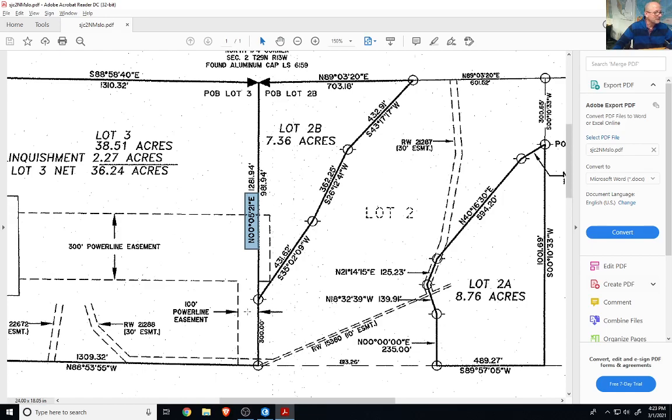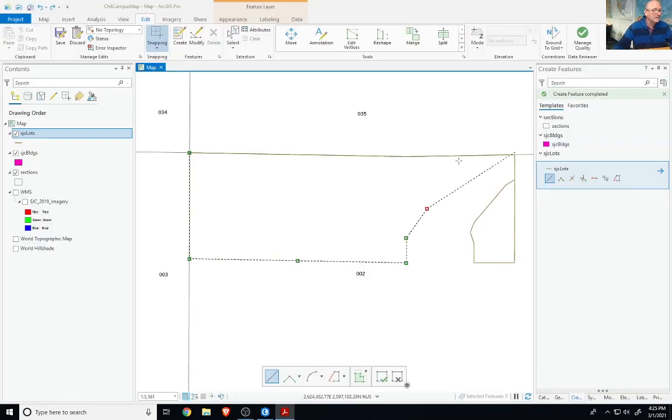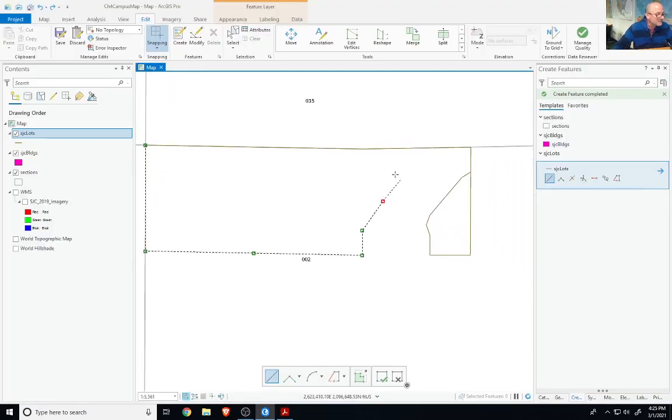So since I can just connect that, I'm just going to take these next three lines, close that off, and then close this bottom line off, and this line, and that's probably going to do it, I think. So when I'm drawing in here, this is the last line before I can just connect to the top of the line that I've already drawn where there's a vertex waiting for me. So I notice that it's in the northeast direction, so I don't have to type that in.